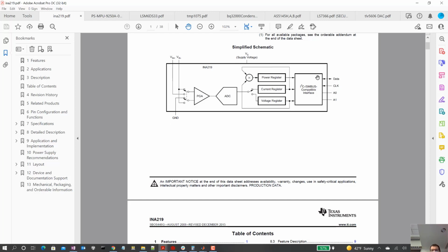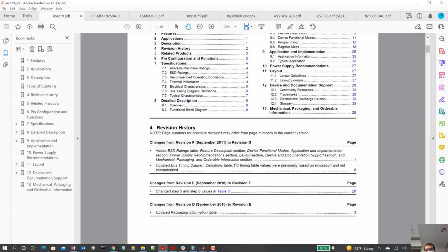And look, they labeled it a little bit differently. I don't really know the difference between I2C and SM bus, but they're very similar. I don't know exactly the differences there. Sometimes when you see SM bus, that's also I2C. There could be a slight difference. Then there's data and clock. Our data is SDA and clock is SCL, so that's interesting, they label it differently. And then there are these 2 address pins that allow you to change the address as you want it for this device.